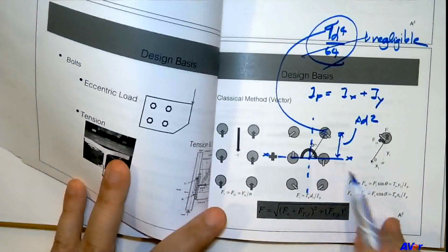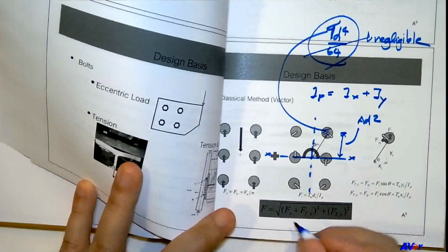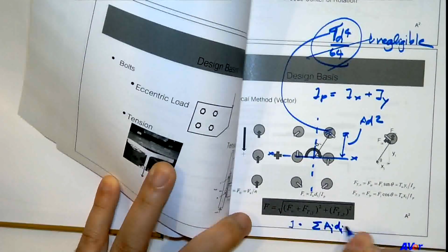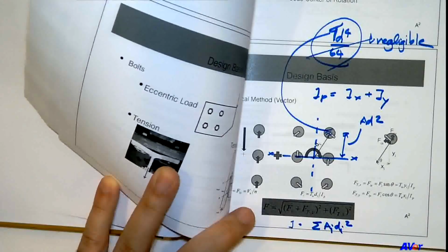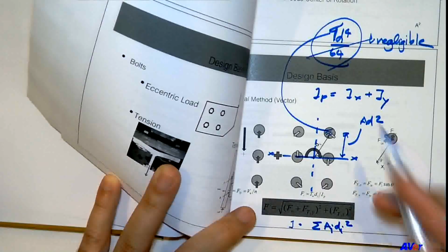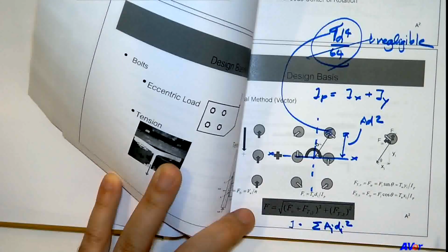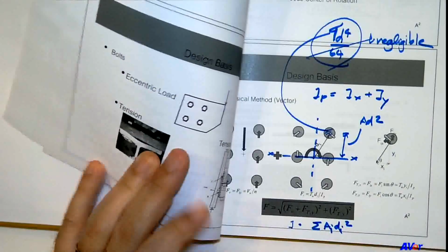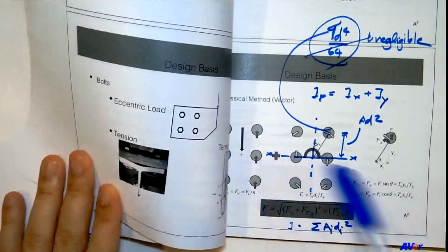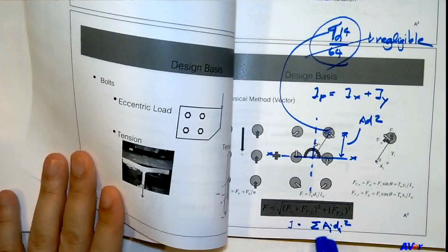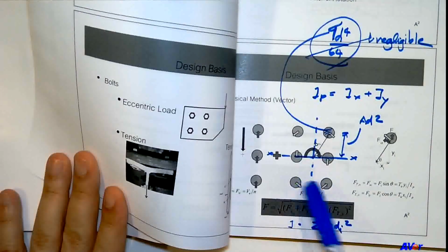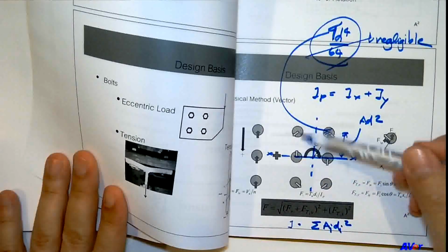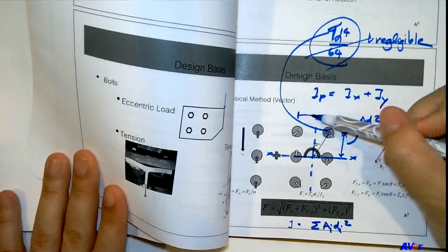So that means the moment of inertia in each axis, we can just say it's the summation of A_i d_i squared. So if you want that, it's fine. If you don't want that, it's also fine, right? And for Ix, for this example, would be the summation of the A d squared of these bolts. And the Iy would be the summation of all 6 bolts because the d will become this distance, right?